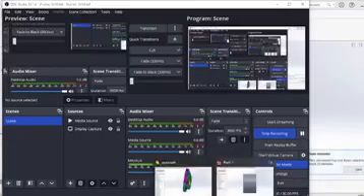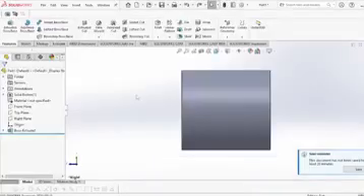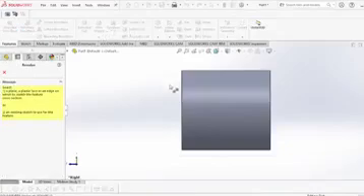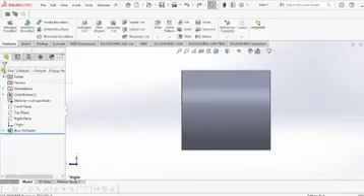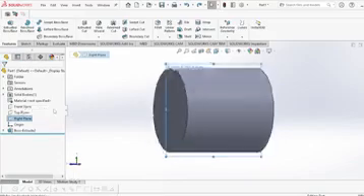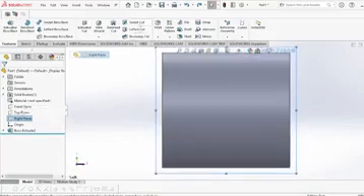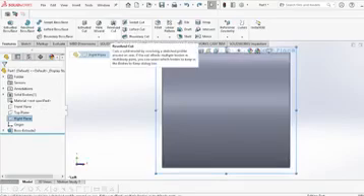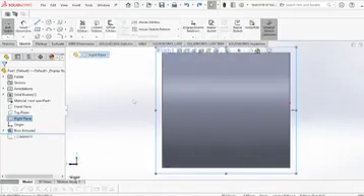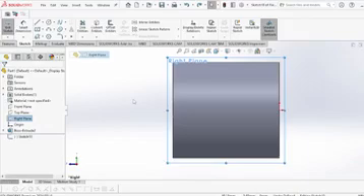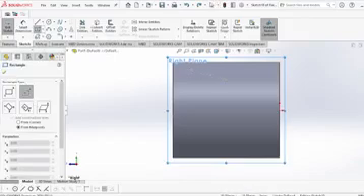Okay. Back, come to the revolve cut. We're talking about the revolve cut. Pick right plane, make it normal, then navigate here, select the revolve cut, hit your Z key to shrink it down, and let's use this rectangle,